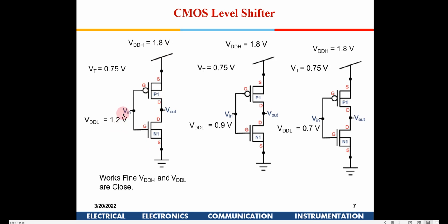But from 1.2 volt logic level to get it to 1.8 volt logic, there are certain issues which we will discuss. That is why we are discussing up conversion. Down conversion is not a very major issue. Now, not only for different technologies, within the same technology node also, we have learnt about dynamic voltage scaling in our very first class, wherein for some circuits which are not in the critical path, you can reduce the power supply there, so that the power consumption is reduced.